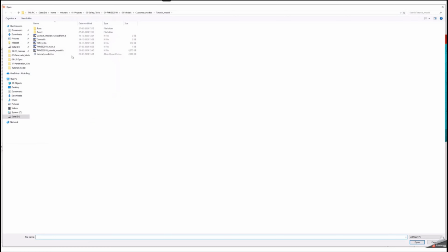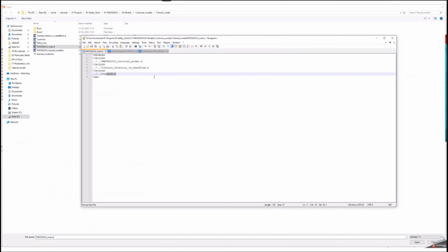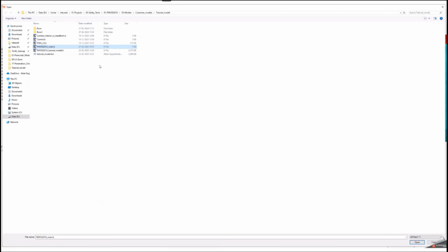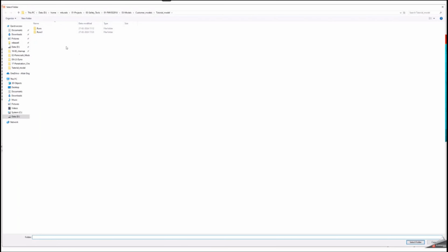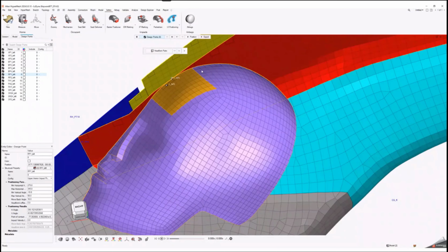For the export, same as the ejection mitigation tool, one can define the export parameters there, like the main file and other control files to the main file, and one can define the head form file and the output directory. Nodal transform or include transform can be used for LS-DYNA. For Radioss there is a submodel or the GRNOD that can be exported. And for PAM-CRASH, a normal group entity with the transformation card can be exported. Select the output directory and export.